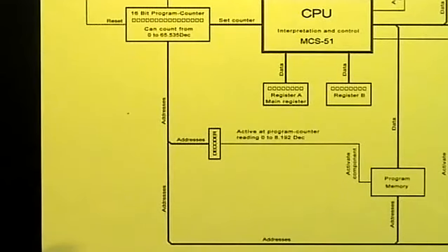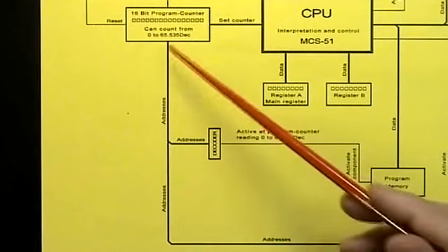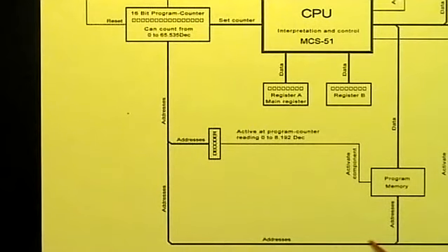If the system is switched on and the program counter is set to the value 0 by the reset circuit, the first memory location of the program memory is addressed via the address bus. The program memory then transfers its memory contents, which it has stored at the address 0, to the data bus.